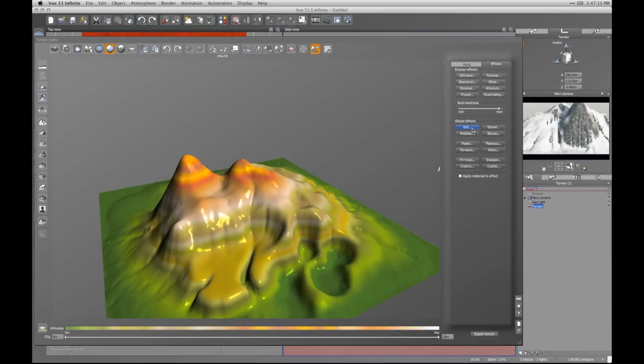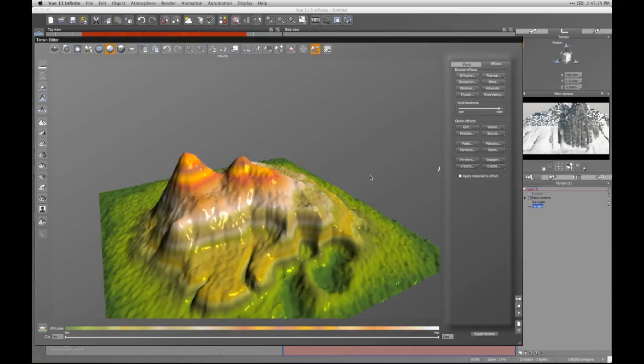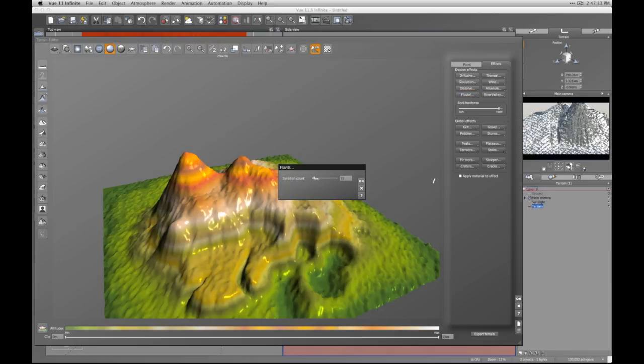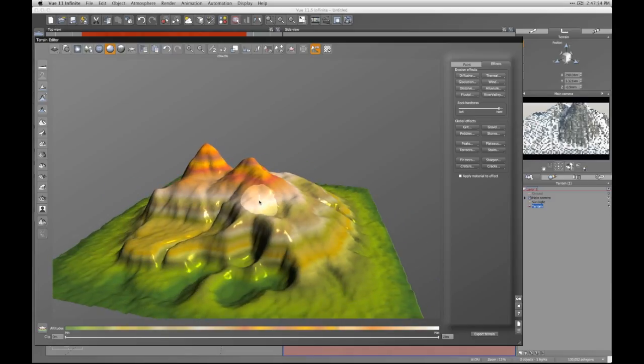If you right click on these, you'll see that it's got usually some iteration count. So that did 10 iterations. An iteration is like it's running through the math, this time 4 times. Which is quite handy, especially when you want to do these fluvial. Sometimes you want to do heaps of them. So if we said, okay, we'll do it 20 times. Hopefully this doesn't take too long. It's going to go through doing fluvial erosion, then more erosion, then more erosion. So it's going through the maths multiple times, in this case 20 times. And so there's our nicely eroded terrain.